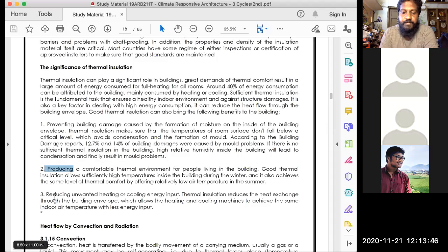Normally, if you are studying site planning, you have been studying climate and what orientation to follow for a building. The reason why we look into orientation is, one, yes, to capture wind, the air movement. The second, a primary part, is that we try to shade or safeguard all the heat-gaining sides of a building.